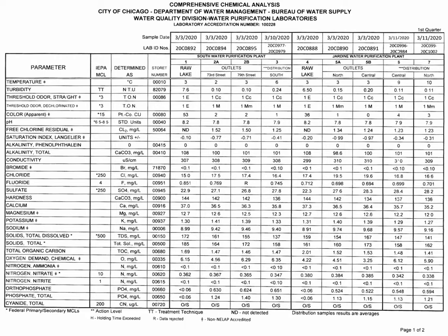The Langelier index is important for some rural areas where you might have high calcium, magnesium, or total hardness. That would indicate whether your water is scaling or non-scaling. The City of Chicago water is just barely scaling. As you can see, the Langelier index across it is quite low. It's negative, so that means it's non-scaling. And it's low too.